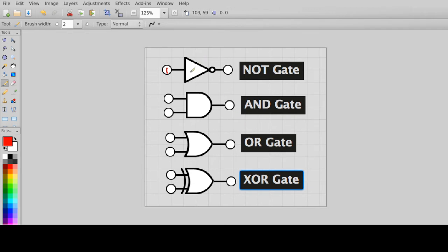The NOT gate does something; there's some circuitry inside of it. I'm not worried about that circuitry right now; we'll worry about it in a minute. What comes out is a 0. So basically the NOT gate will change that 1 into a 0. Conversely, if I feed it a 0, let me write it above, that's a little bit better, a 1 will come out, because that's what NOT does. It changes 0s into 1s and 1s into 0s.